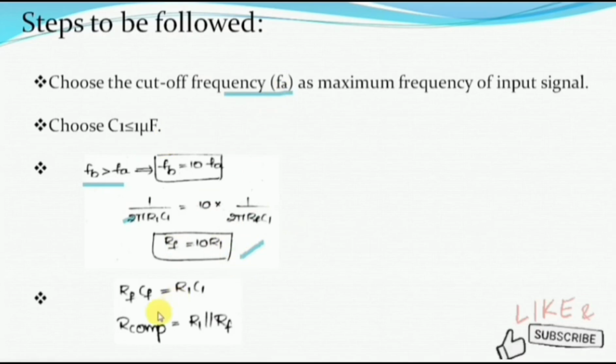Finally, RF C1 is equal to R1 C1, so CF is obtained. We know the values of RF, R1, C1, and from this we can obtain the value of CF. At last, the R compensation value is R1 parallel to RF. If you follow these steps, we can easily design the differentiator circuit for the given input signal frequency.